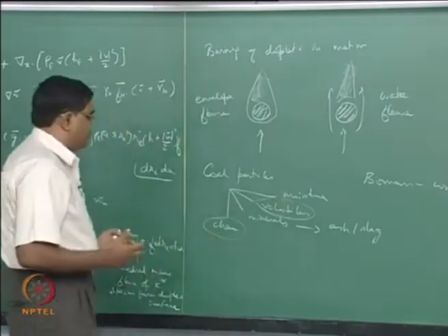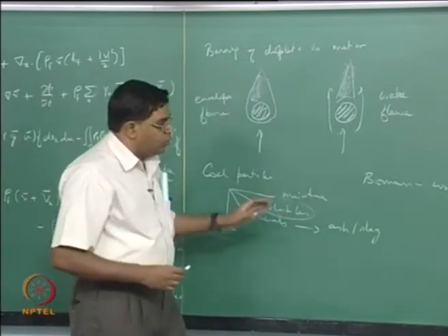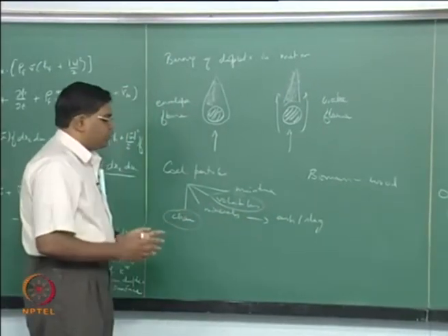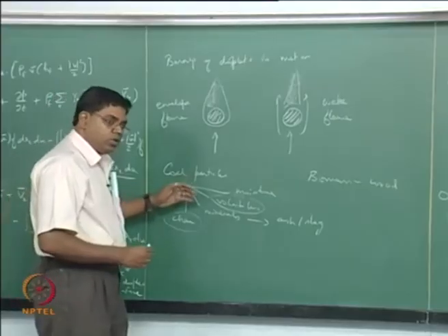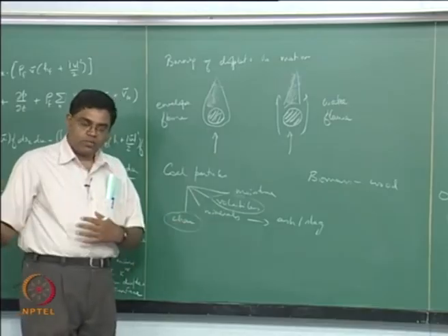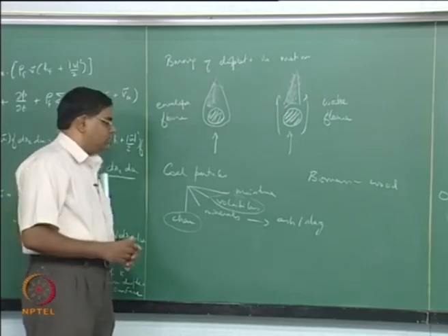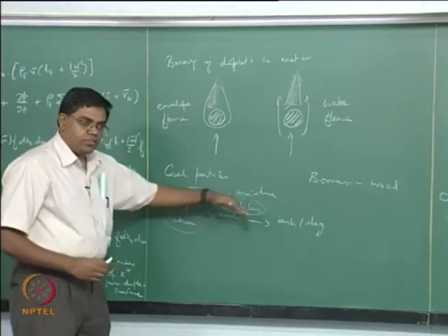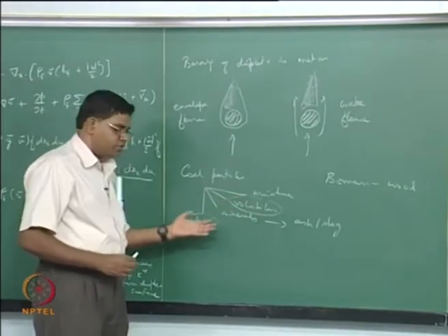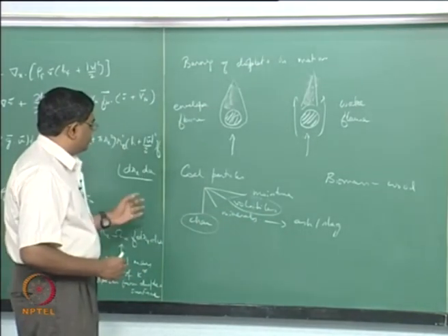Typically one of the major problems with biomass and coal, more with biomass because you have varied kinds of biomass in the first place, but even for the same kind of biomass and for coal, is that different locations where you mine or harvest them give different compositions. So you have to do the proximate and ultimate analysis first to get an idea of what kind of energy content they have and what kind of ash problems you are going to face.